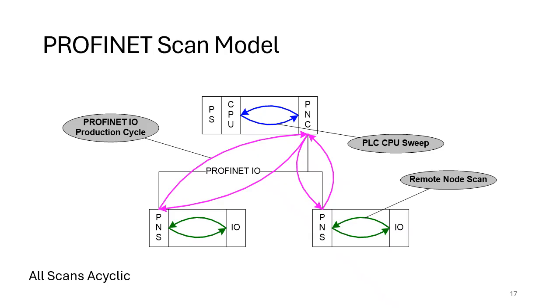And the worst case is normally each of those scan times added to each other and multiplied by 2. That would be your worst case. Your typical case is that you hit all of the scans at exactly the right time and everything happens very quickly, within a millisecond or less. So that means your typical scan time is the average of those two.